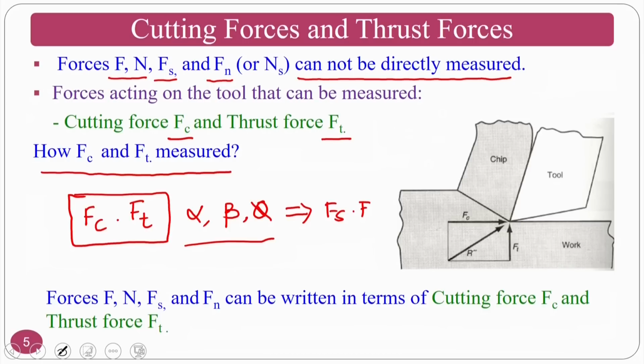That means these are all measurable. Okay. From the Merchant circle relation, you can calculate all these forces, frictional force, shear force, and other things.